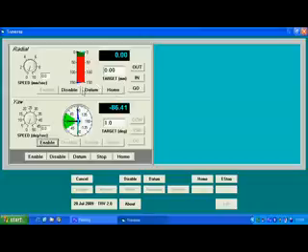The first thing we do need to do after switch on is to datum the actuator, and what this will do is to move the actuator back out to its radially outward limit switch. It then moves forwards a little bit to find an index mark on the encoder, and then it sets its datum from that index mark, so it will be just clear of the microswitch. We don't need to set the speed to do that. The speed is automatically enabled from the initialization file.